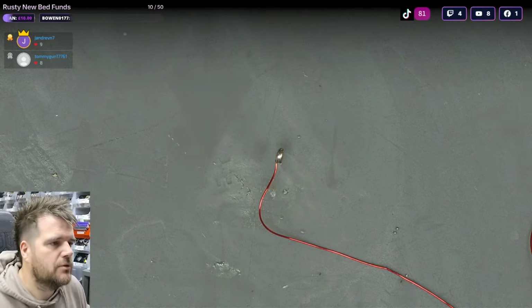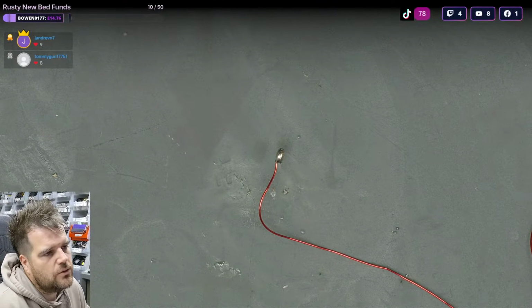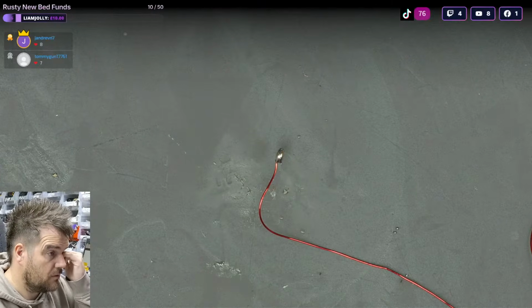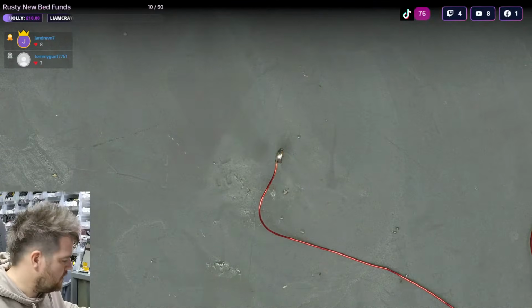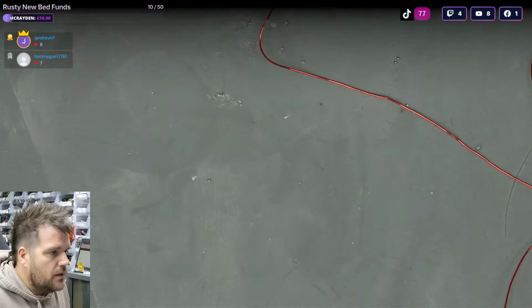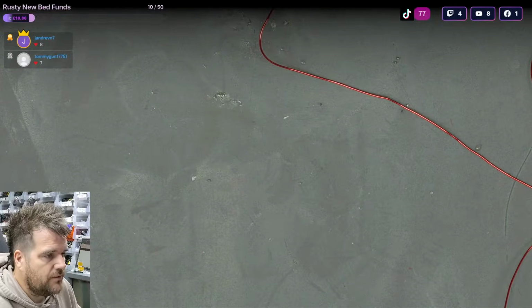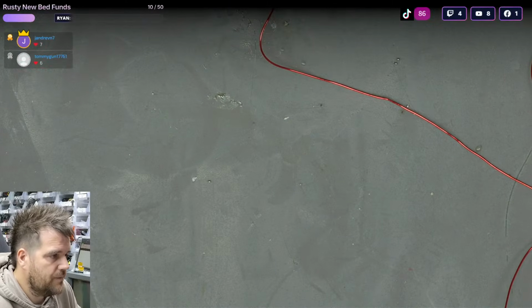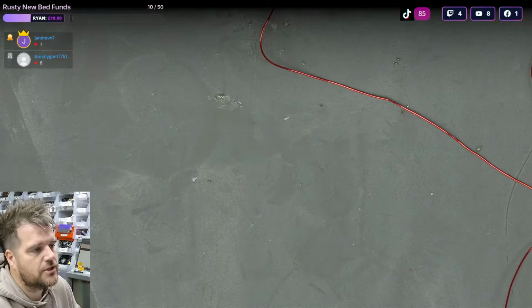I've got red light boot but no sound. Yeah, so ignore the screen completely if you've got no sound but you've got red light boot. Go to the wiki and go to reading game cart. You need to check if you're comfortable reflowing the A6. I'd reflow the A6 just to be safe. Reflow the Z80. If you don't want to do them, then you don't need to, but that's the first recommendation.